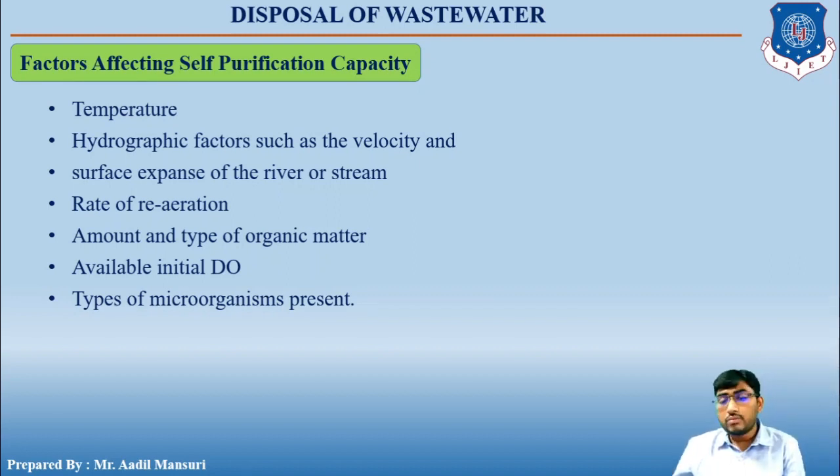Now, in a swiftly moving stream, that is with high velocity, the oxygen is replenished quite quickly. The water surface at the air liquid interface is being continuously replaced by the turbulence of the stream movement. The oxygen saturated layer is overturned and replaced by an oxygen deficit layer. In this way the oxygen saturated liquid is rapidly mixed throughout the stream to supply the microorganisms with sufficient oxygen. Now too high velocity is also not preferable because it will create a lot of turbulence which will scour the bottom of the bed, increase turbidity and retard the algal growth.